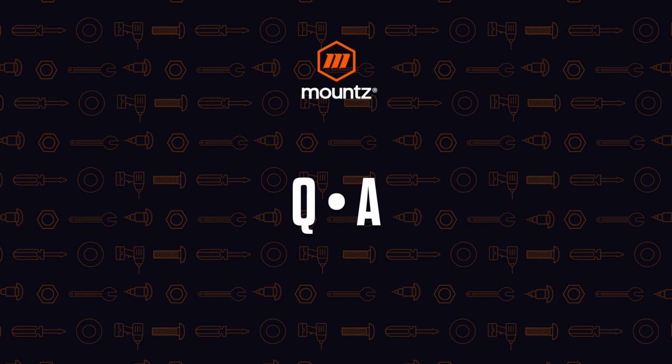All right, thanks, Dave. Next question was, when you measure the dynamic torque, what items can influence the torque on the fastening joint besides the soft gasket that you had shown? So you have quite a number of different variables that can go into producing the final torque that is given. Not only is the gasket one of those influencers, you have if there's any lubrication involved. Is the fastener lubricated with Loctite or with oil or anything like that? That's going to change the coefficient of friction. You're going to get a much greater clamp force at the same torque value for that particular fastener.